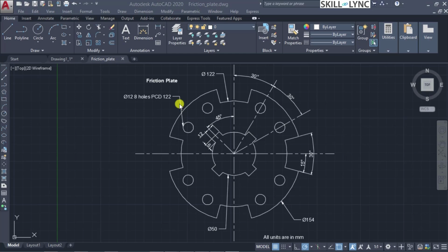So these layers are kind of equivalent to the overlays that we use in paper-based drawing. It means that we overlay one set of images over the other. So these are going to be the primary organization tool for us in the drawing. So we repeat, layers are used to group information by function and to enforce the line type, color and other standards. So we'll look into how these layers can be used and how they can be categorized.